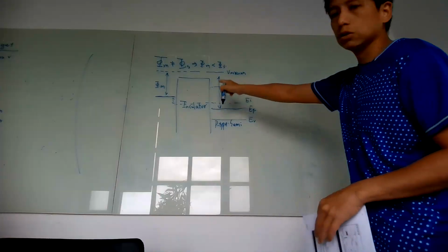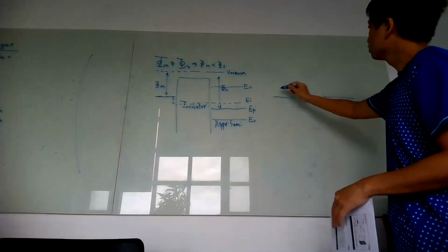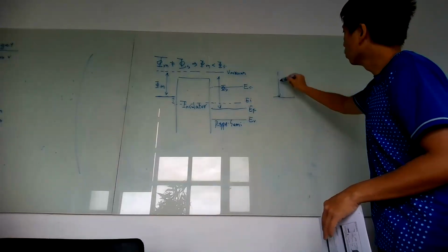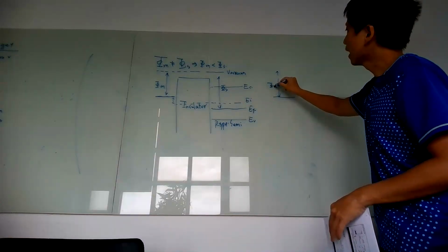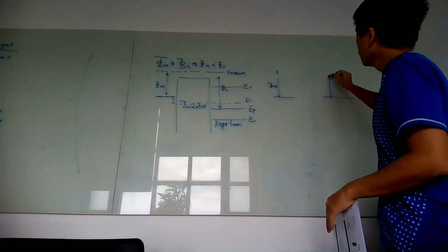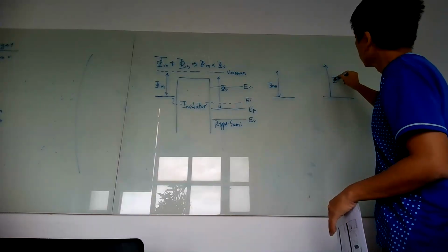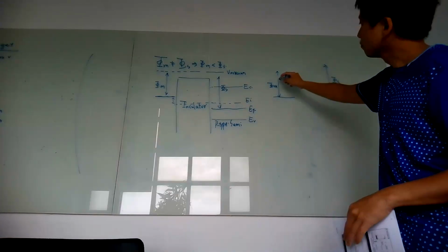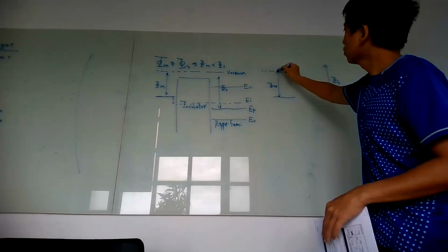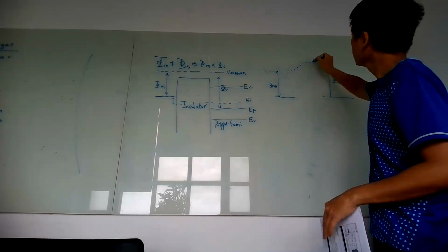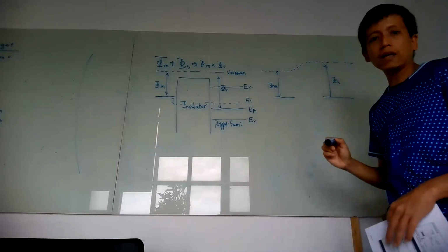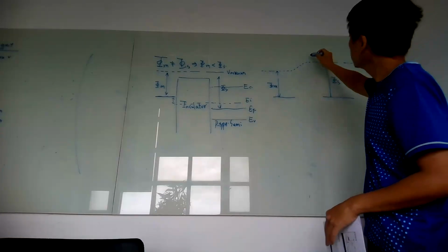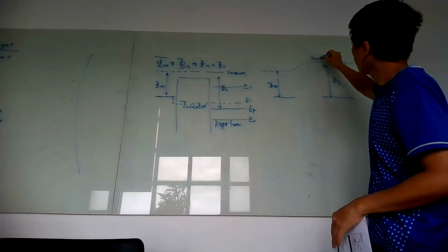So you can think that we first align the metal layer here. In between the insulator, we get the metal, with the work function of the metal, phi m. And here there will be a bias. Okay. As we mentioned, the bias is larger than phi m, so you can see the vacuum level should be bent upward.